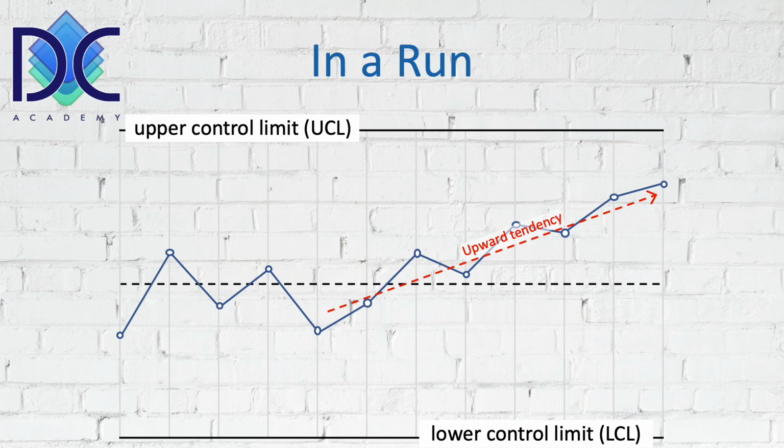A process in a run: what we see here is an upward tendency. From a certain moment, we see that the averages are going up, which basically means that there is something going wrong with the process. Also here, this is an indication of a problem. We have to stop the process, verify what's happening, and adjust it. The faster we adjust the problem, the faster we will have, let's say, high quality production again.